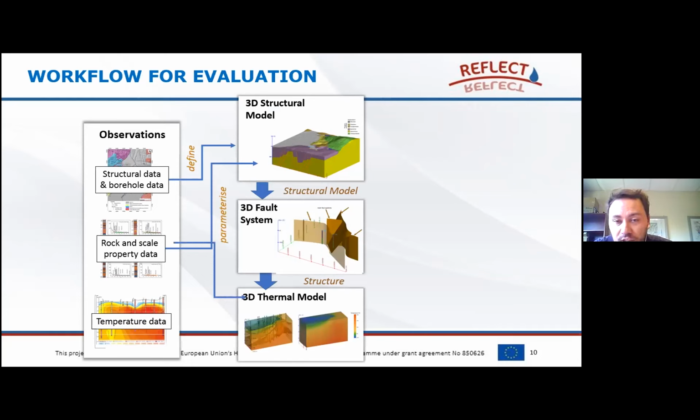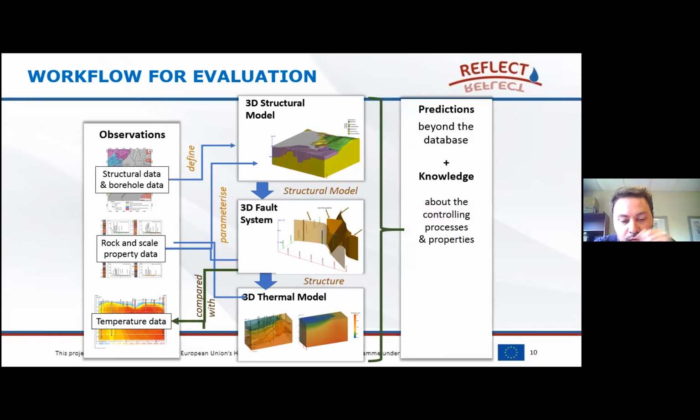The most critical factors are determining the reinjection temperature, and revealing the mineral saturations depending on the temperature and pH, of course. As you know, mineral saturation diagrams are diagrams used to show the scale types and possible scale types that may occur in the geothermal power plants and surface equipment system.